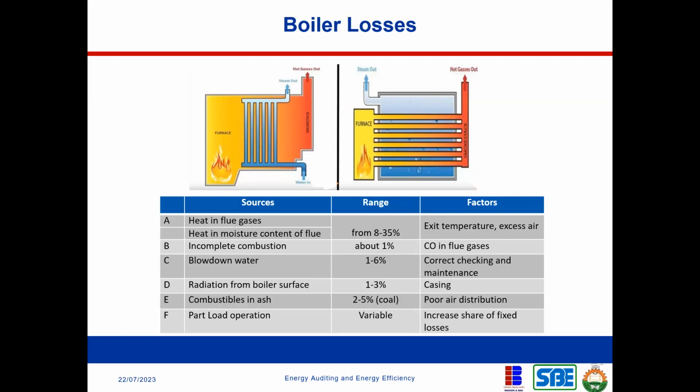So over time, you need to flush out those solids, those impurities, right? So when you open the bottom of the boiler to allow those dissolved solids to flush out, heat is also being lost in the boiler system, because you're opening it to release hot water in the boiler with the dissolved solids. You want to flush them out, so heat is also being lost. So you need to recover that heat that is being lost.